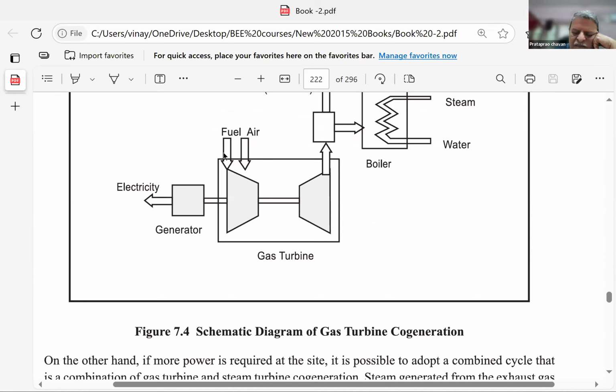Normally, the fuel here is gas. It's a gas turbine. So gas plus oxygen in the air gets mixed under high pressure. The combustion takes place here. The high heat generates very high temperature flue gases, and the gases are exhausted through this turbine.